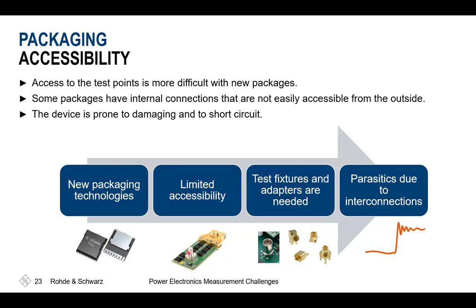Just think about it: if you have not considered a test port or test point on the board, and you're adding connectors via a short wire to the testing points, please always keep in mind that each millimeter of these wires will add about 1 nanohenry of inductance into your system. So worst case, you're adding so much inductance that these circuits become resonant, and then you might even destroy your semiconductor by just adding the test point.